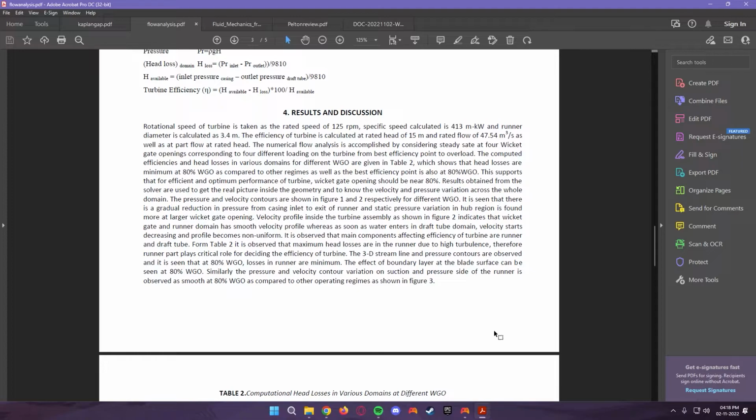In this paper, they have used CFD, which is one of the tools to evaluate the efficiency of alternate designs of turbines for optimization. Under this paper, CFD analysis has been carried out to evaluate the part load efficiency of the Kaplan turbine under different operating conditions, so a range of part load efficiency for the Kaplan turbine is determined.